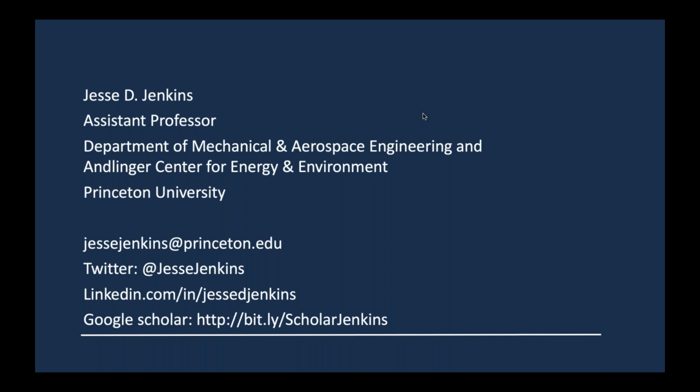And if we charge the vehicle in a coordinated way, that could be a very flexible source of demand, and that could substantially reduce the need for energy storage. It's essentially another fast burst technology. And in our study, we looked at a case where we assumed 20% of all demand was shiftable by 8 hours for free in the optimization, just to see what would happen. And what it did was it basically displaced the need for batteries one for one. So the more flexible demand we unlock, the less we need to deploy more costly battery storage.